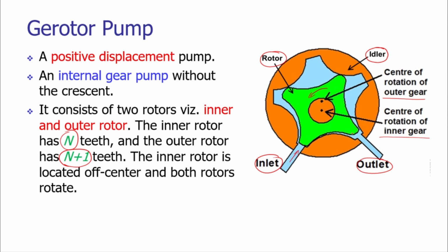but the rotor is continuously rotating. As the fluid is getting inside, the rotor is driving that fluid inside the gap of the rotor and the idler. The gap is small, so that's why there is an increase in the pressure of the inside fluid. The rotor is driving the idler and it is also driving the fluid with increase in the pressure, as the pressurized fluid will come at the opening of the outlet port. Through the opening, the pressurized fluid will come out of the pump and that will be applied to the load.